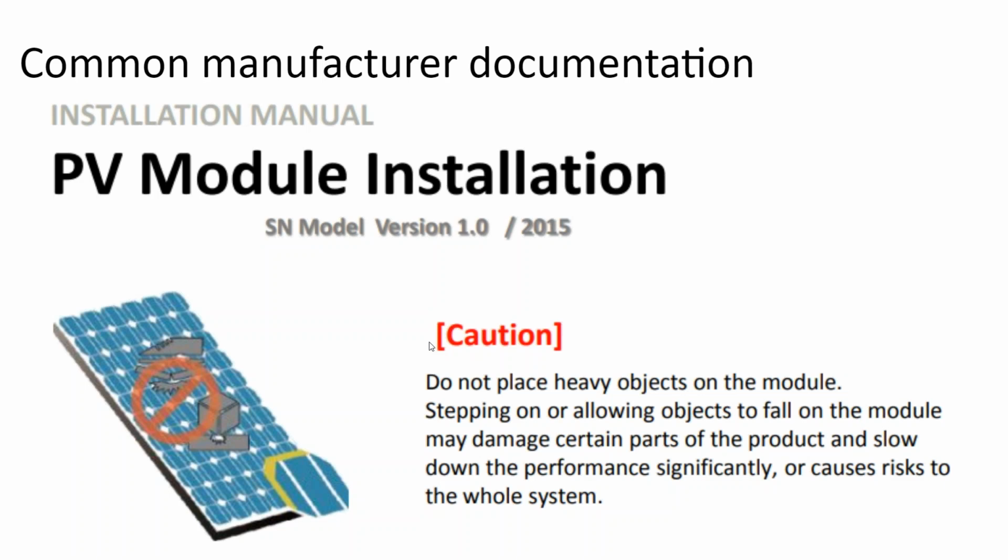So the moral of the story is, treat the surface of the solar panel with respect. When you're handling a solar panel, you should really just be moving it on the frame. Panels are big, and sometimes you have to slide them across the surface rather than be able to grab them and lift them up in the air. And if you're sliding a panel across the surface, like sliding a panel off of a pallet, you always want to make sure you're just impacting the module frame itself and not the surface of the glass. So even if you're sliding a panel, make sure you're staying off the surface of the glass.